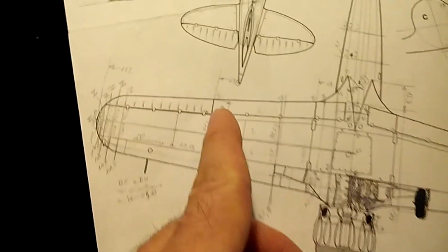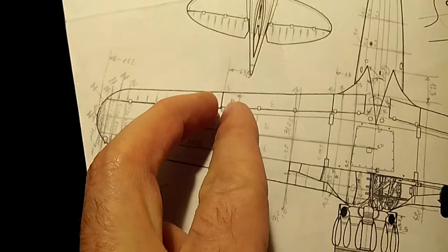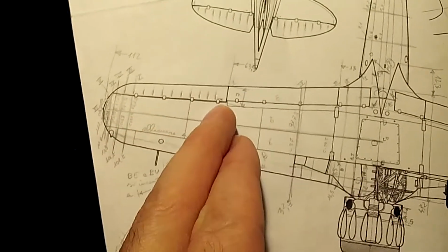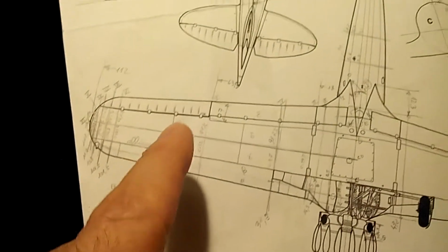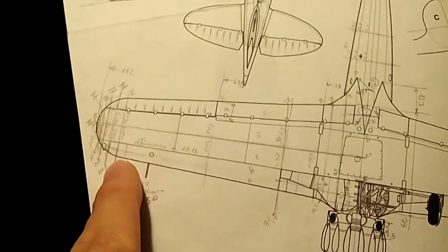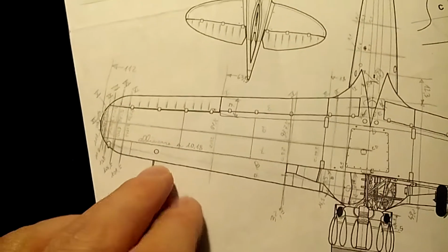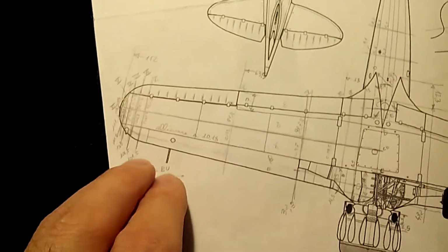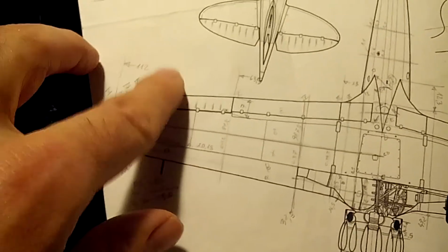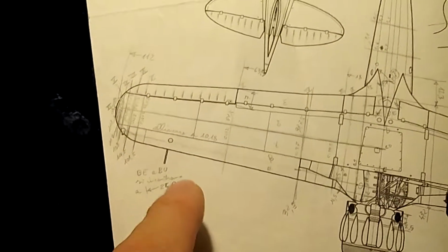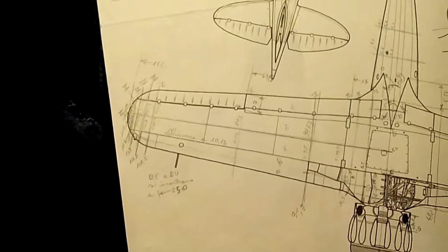One must be counted where the flap ends and the aileron begins, 2 if they are not on the same line, another one here, and you must choose to make more subdivisions close to the wingtip, depending on the shape of the wingtip itself. More subdivisions are needed for a rounded tip,